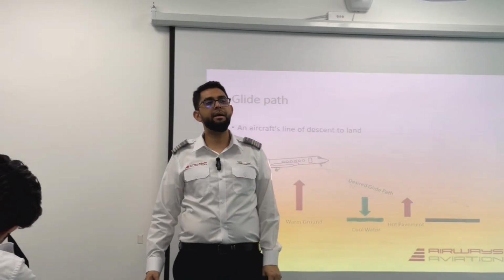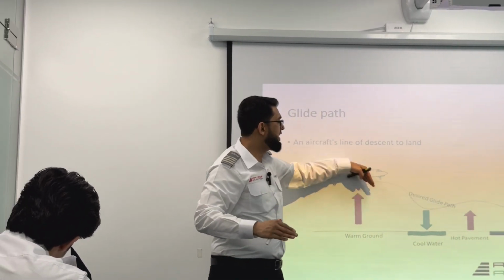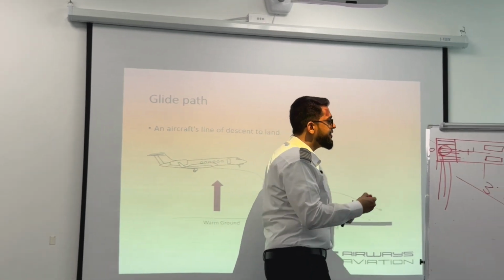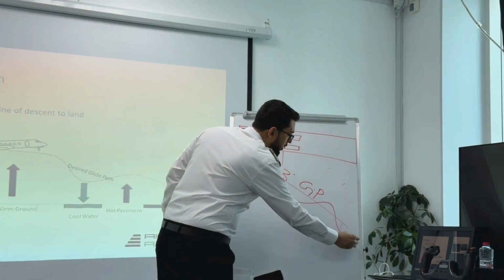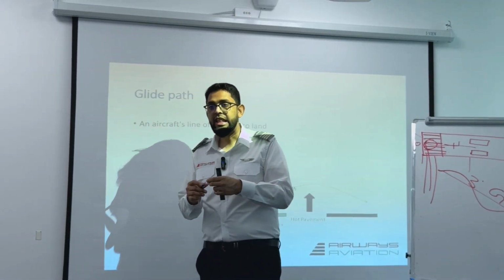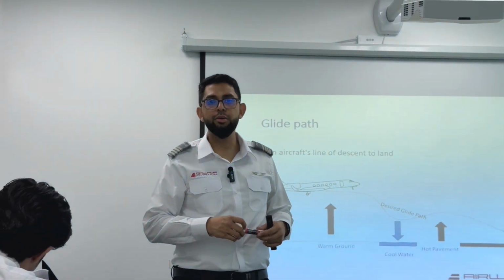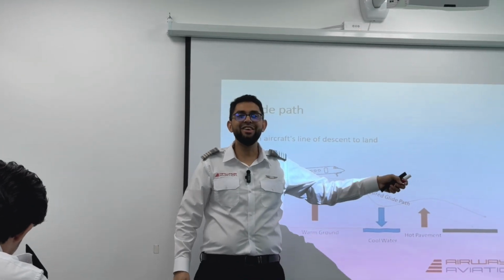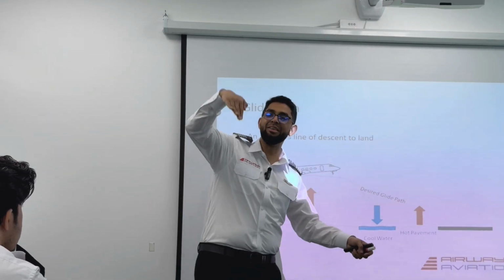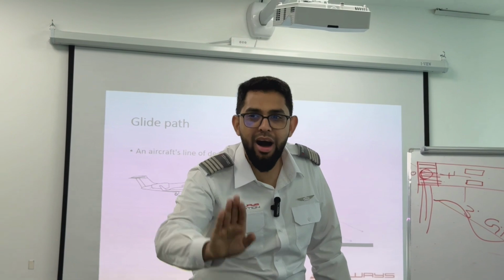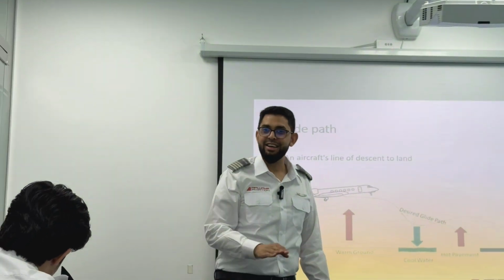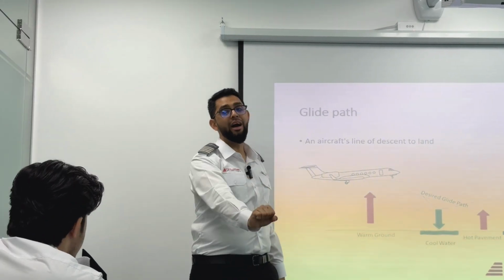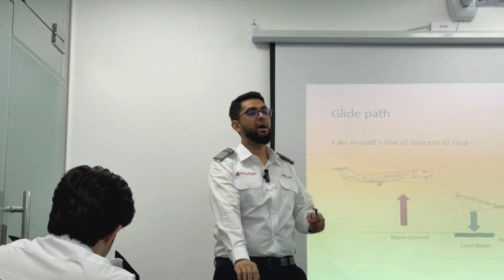And if you're a horrible pilot, you'll be doing that wavy line as you see. Now, imagine if you're doing this all the way to your runway. That means either the winds are troubling you or you are a horrible pilot yourself or whatever the reason is. Do not go and touch down on the runway with that kind of an approach. Snaking throughout the approach, you're unstable. You're not ready for the landing. You'll hurt yourself. Go around. Full power, pitch up, go.